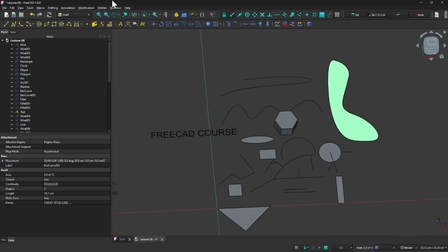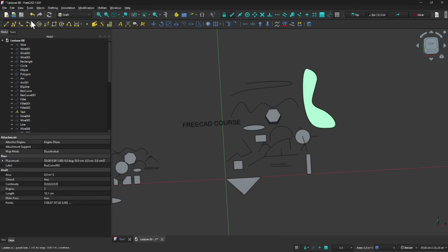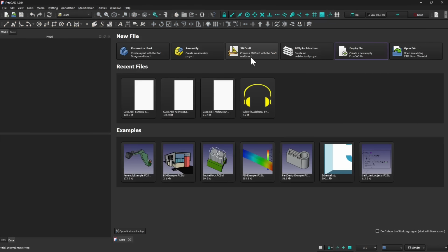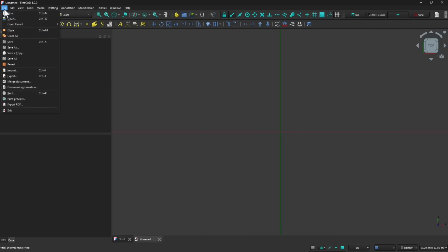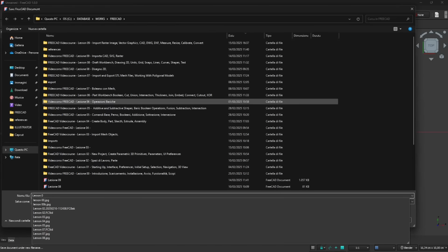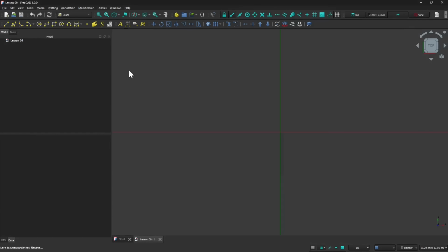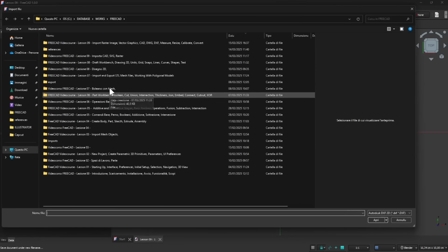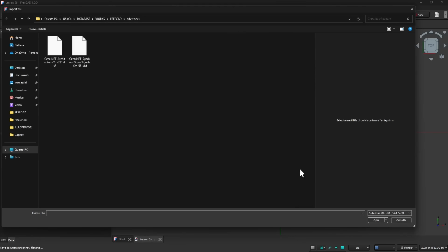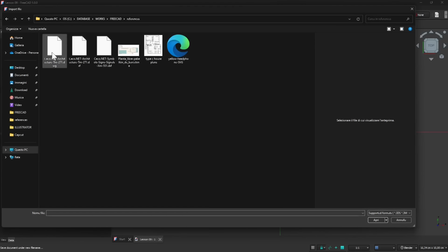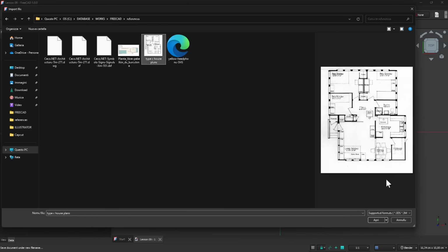Okay, so let's get back here, and I'm going to close this and create a new one. I'm going to close and start again with a 2D draft interface. I'm going to save this as lesson 09 and import. So how do we import an image? Well, it's basically the same process that we used. We can go here to File, Import, and just navigate into the folder. I saved my image into this folder right here, among others, you see here, assets. So I want to use this one and open.